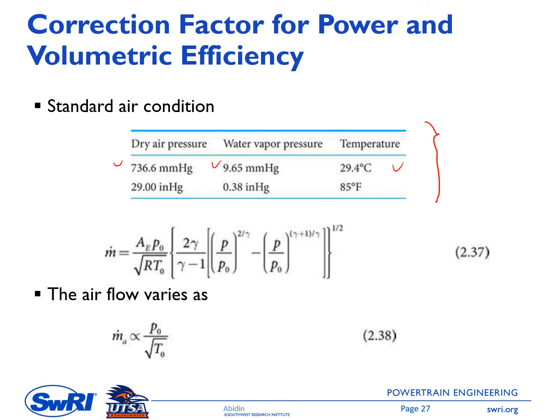And we use the orifice mass flow rate equation, so it should come from the fluid mechanics class. This mass flow rate is a function of the total pressure to the static pressure. So this is the mass flow rate through an orifice, and we have upstream total pressure and then downstream static pressure. From this correlation, we know that the air mass flow rate here is a direct function of the pressure and the square root of the temperature, equation 2.38.